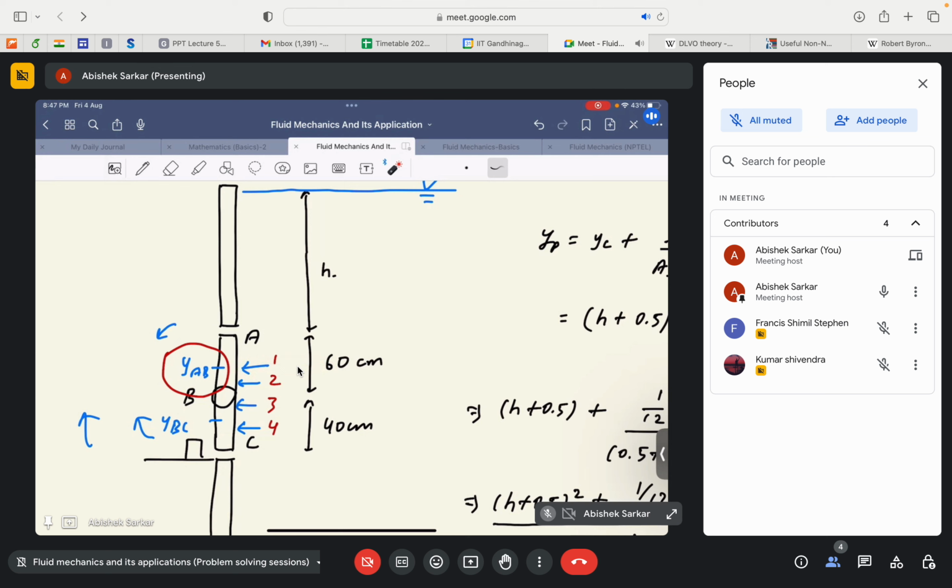Yes. Why? Because this will essentially give a counterclockwise rotation to the plate which is hinged at point B. So the gate will rotate in the counterclockwise direction, causing the gate to open, right? Because there is no stopper here, so the gate will open. Similar to that argument, at point 3 also the gate won't open, because it's quite close to the hinge, but still it's below the hinge, so the gate won't open. So according to the need of our question, the point of application should be at point 2, so that the gate just opens, right?